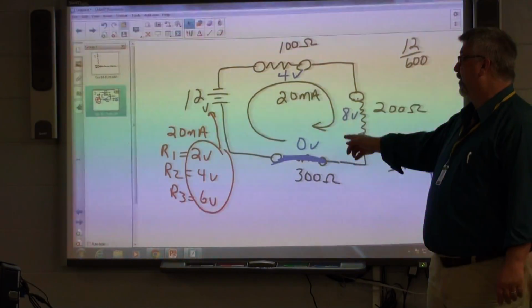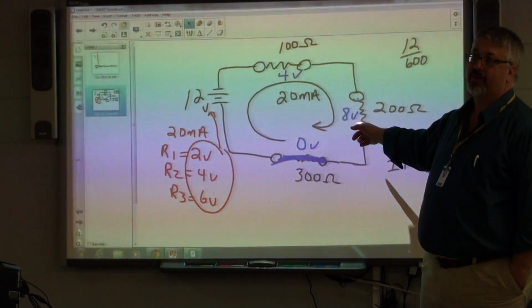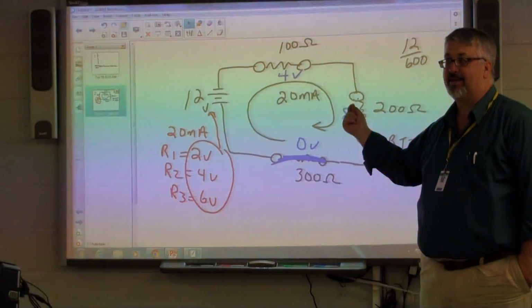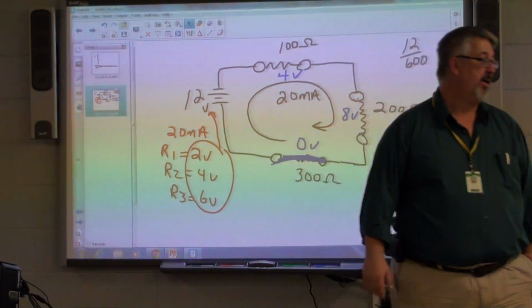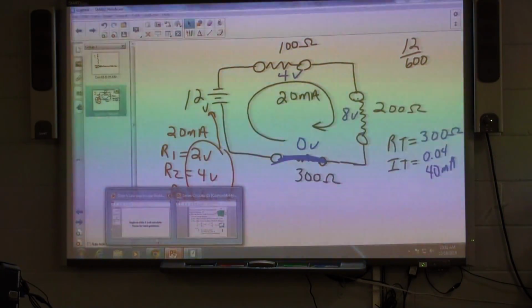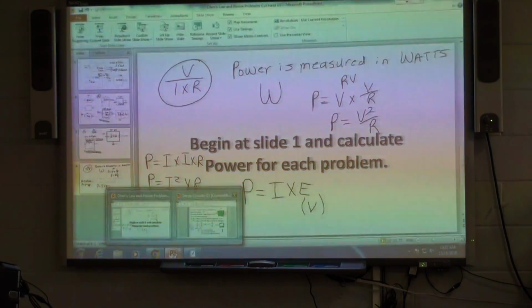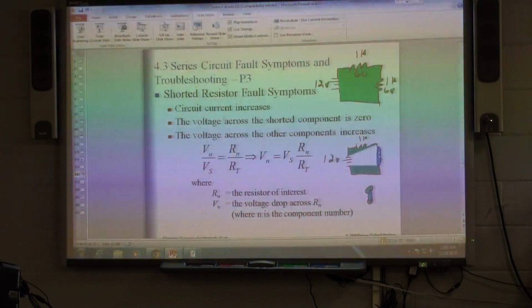It would bring it down to probably like 3.98 volts and 7.96 volts, and then just a very teeny weeny little drop here, depending on what those values are. So when we troubleshoot, we've got to get a little understanding of what's going on and how these things cause and effect. By knowing these rules, we can know that a little more.